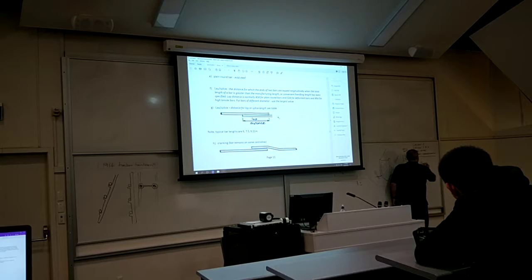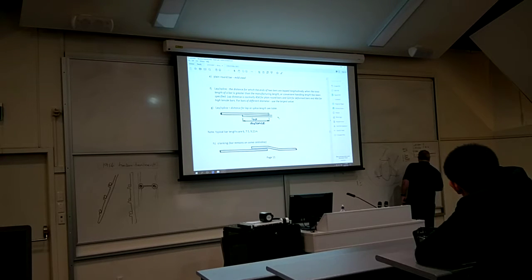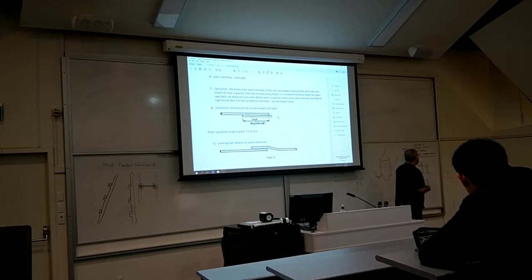So if you were given, say, a 520 lap, that's how far you would do the bar each side past this bar here. Same in that direction. And in a window situation, exactly the same. The lap goes, that's your lap there. So it's not just lapping bars.